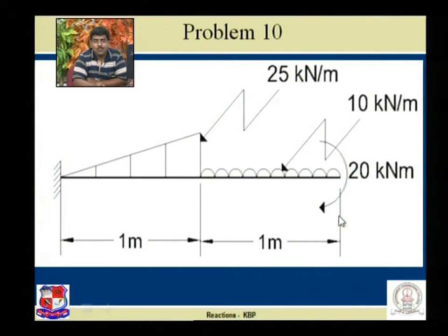They are finding some reactions, I don't know how, as this is a free end and a free end doesn't have any kind of support. When there is no support, no reactions. Only at A, at this support, there are 3 reactions, that is horizontal reaction, vertical reaction and a moment acting at this particular joint.